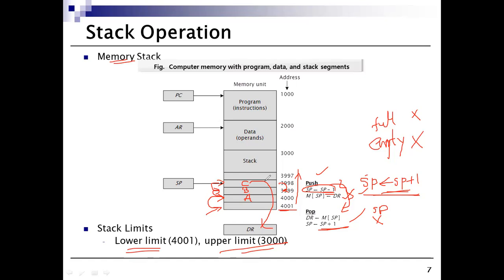I think I'm clear. So you have 4 ways of organizing your stack. Okay, so the stack can be incremental addresses or decremental addresses, and it can be transfer first and after that update the pointer, or else update the pointer first and after that transfer the contents.